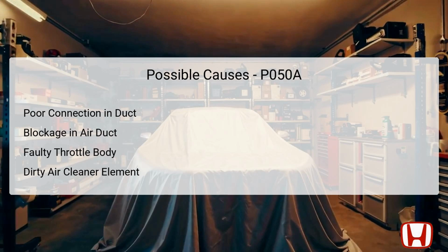A faulty throttle body may not allow adequate air passage, directly impacting the idle speed during cold starts. Additionally, a dirty or obstructed air cleaner element can hamper air intake efficiency, triggering the code. Understanding these potential causes equips you to systematically eliminate each one during the troubleshooting process.